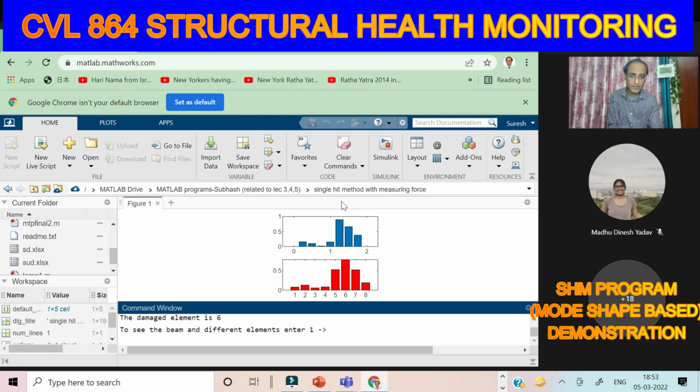The top figure is basically with respect to the nodes. So first we have plotted with respect to the nodes, and then we have converted it into element data. How have we done that? We are just seeing the node number to the left of the element and the node number to the right of the element, and we average that. So we assign that value to the element. The red one is for the element, so we find the 6th element is damaged.